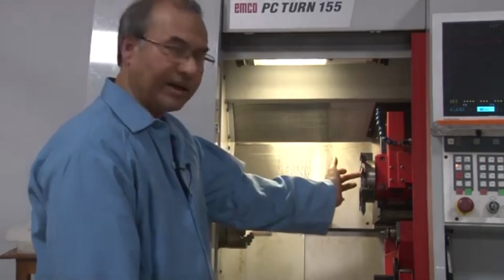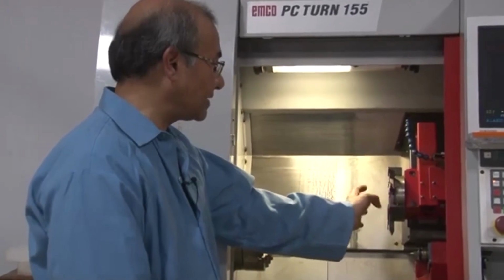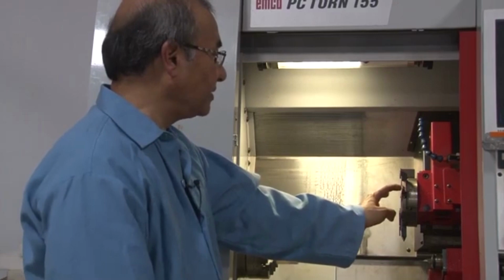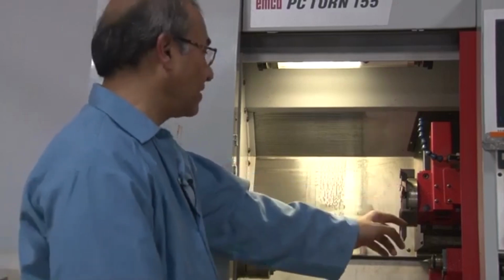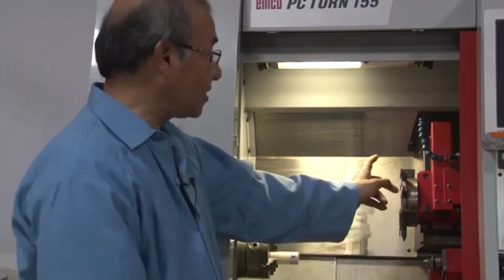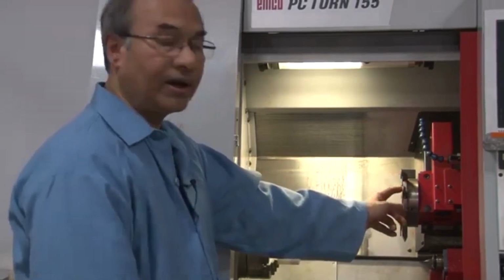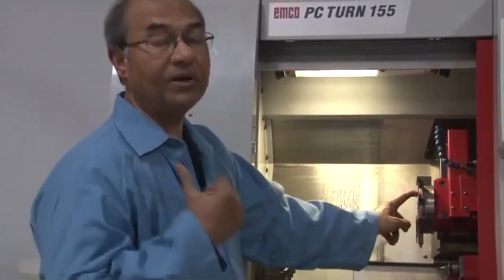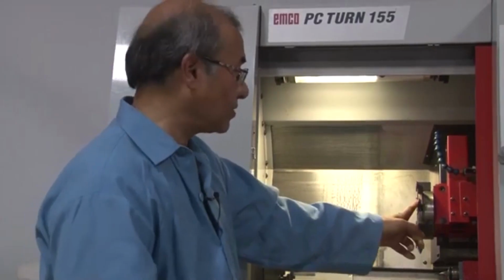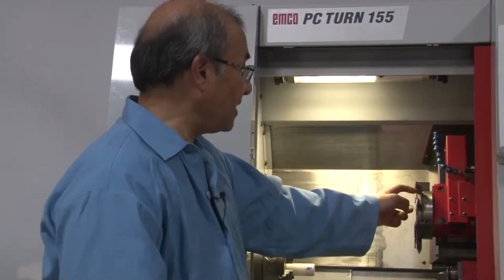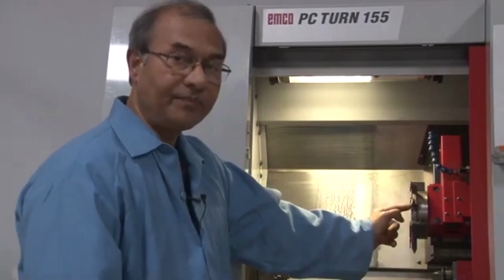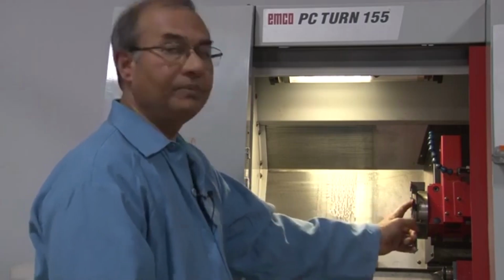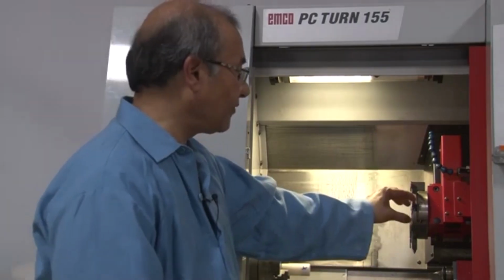Here, this is the turret head, and as I was telling you, the turret head will hold many tools. All right. So, depending on the tool that you require, either it is a turning tool, or a facing tool, or a parting tool, or a forming tool, you have to call that tool in the program. If you remember, we have said T01, so that is one tool, T02 and so on. So, each of these tools in the turret head are numbered. So, according to the number given in the program, that particular tool will come to the position where it will be ready for machining.